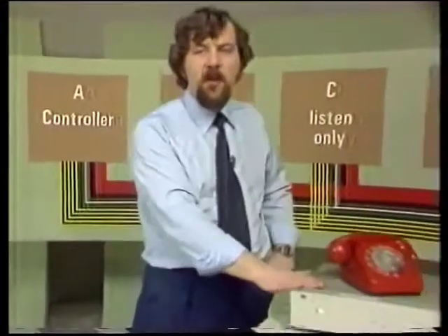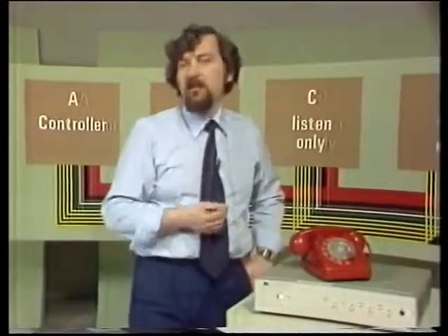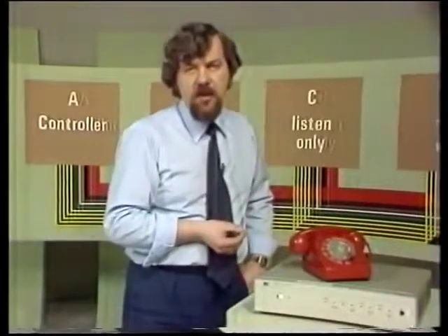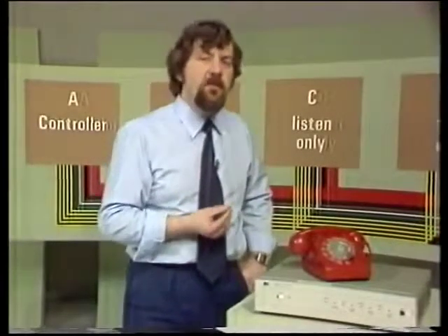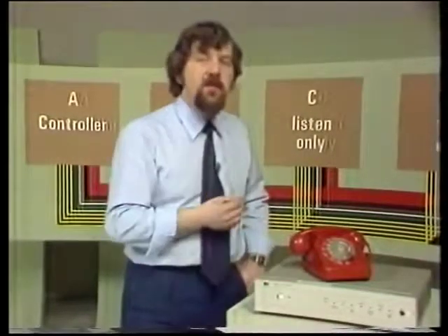But it is possible to buy a device like this, which, through an intermediate post office modem, can connect my bus system here to one, say, in California. The device, it's called a bus extender, converts the parallel data on the bus into serial form, suitable for transmission over the public switched telephone network. At the other end, a similar device converts it all back into parallel data again.